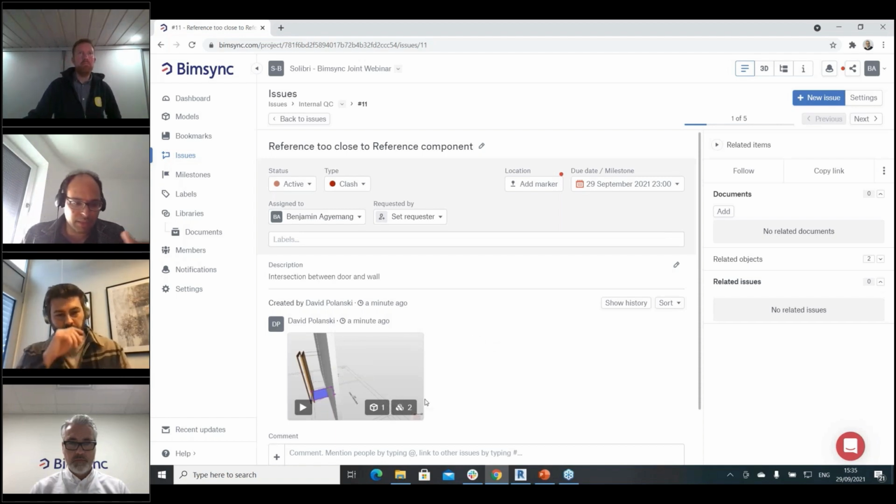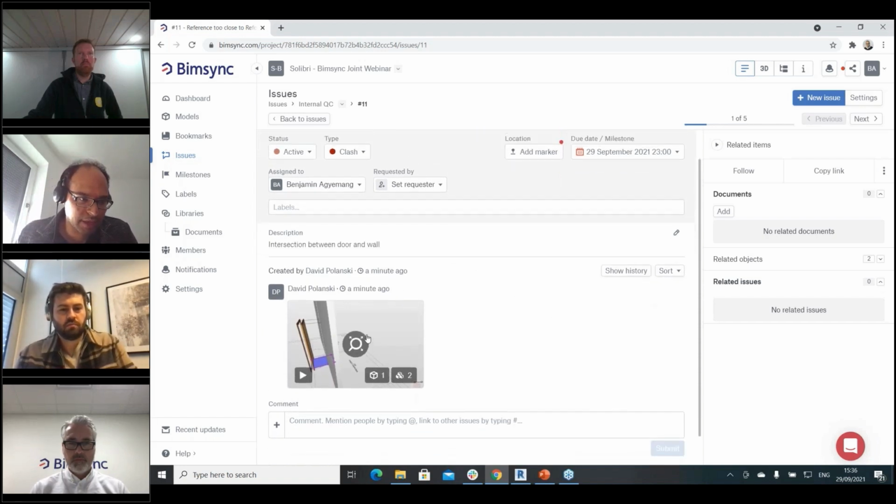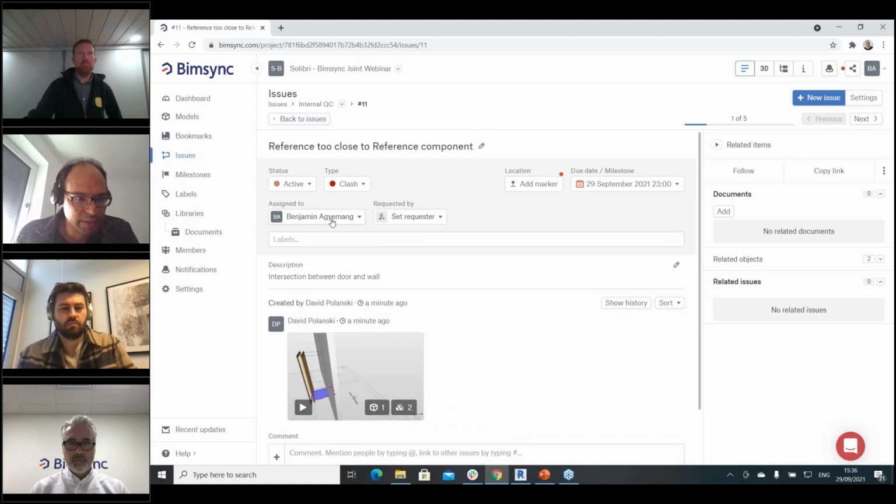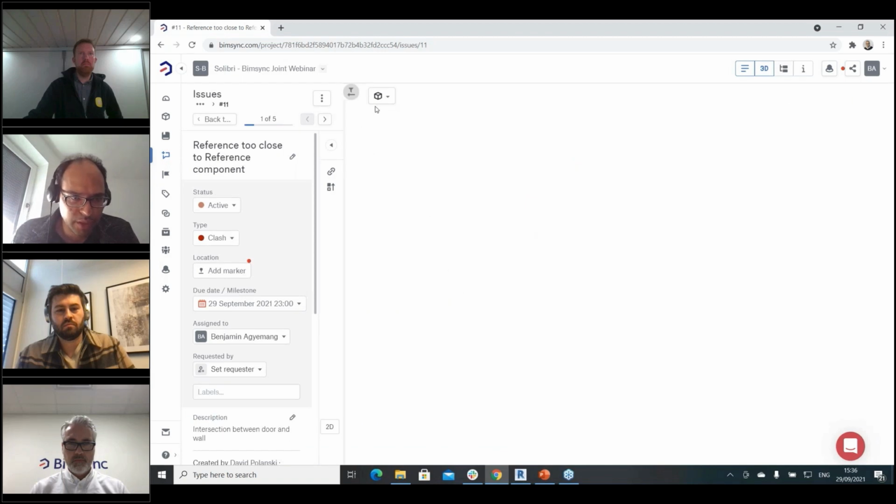What I need to do is go back to my authoring software, connect directly to Bimsync, and get this issue so that this viewpoint could be shown directly there. So let's just imagine that I did everything already on my authoring software, and now I have an IFC model that I could upload fairly quickly.